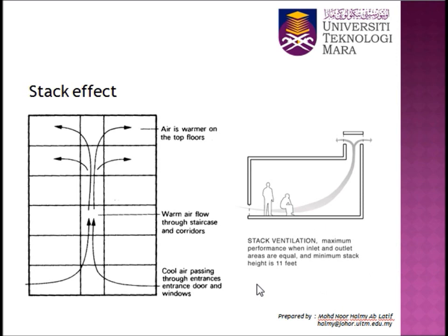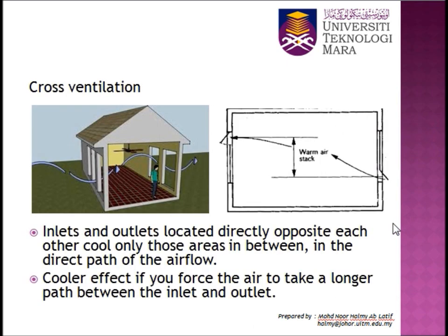So stack ventilation, maximum performance when inlet and outlet areas are equal and minimum stack height is 11 feet. Okay, ni designer should be considered when designing a room or building.